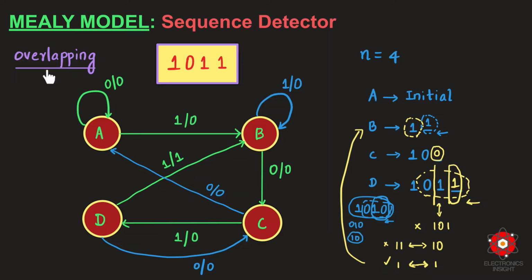The major purpose of this particular slide is to understand the state diagram, because a state diagram clearly shows the transition of the states from the present state to the next state and the output for a corresponding input. In this diagram, a state is represented by a circle, and the transition between the states is indicated by the directed lines, the arrowed lines connecting the circles. Each circle is a state. A binary number can be written inside each circle to identify the state the circle represents.